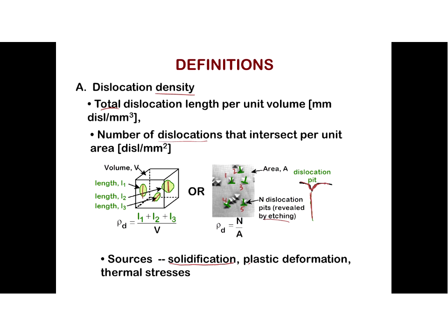Another method is through plastic deformation. As we'll see soon, it turns out that when you plastically deform a material, you're moving entire planes of atoms, and that's creating new dislocations. Fair enough, right? Seems reasonable. If plastic deformation corresponds to atoms completely migrating, they might migrate into a position that is not part of a perfect crystal lattice where their final destination is. So that's a way to induce it. Another one that we'll see, especially when we get towards chapter 9, is thermal stresses and thermal processing.